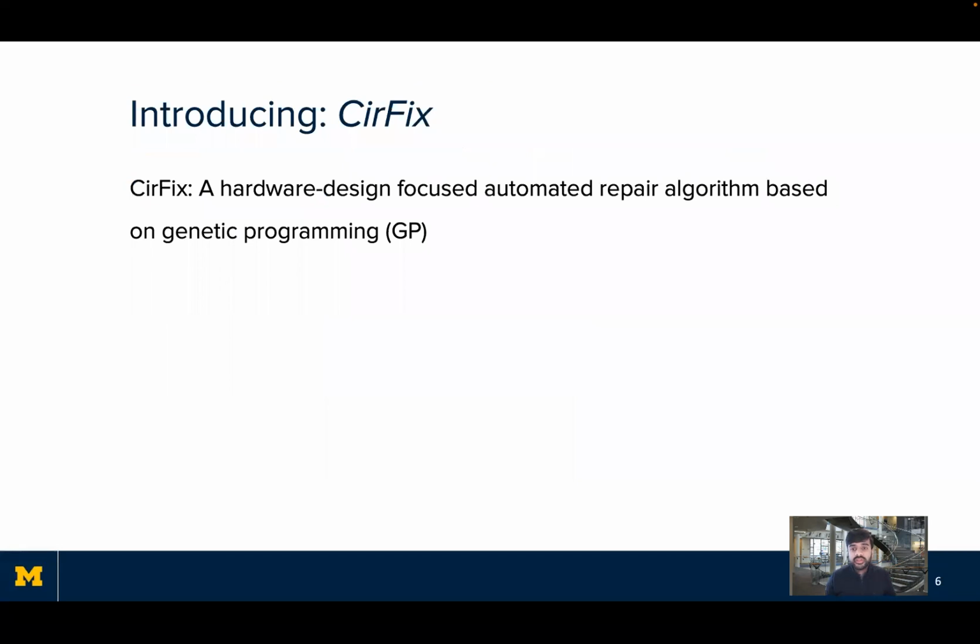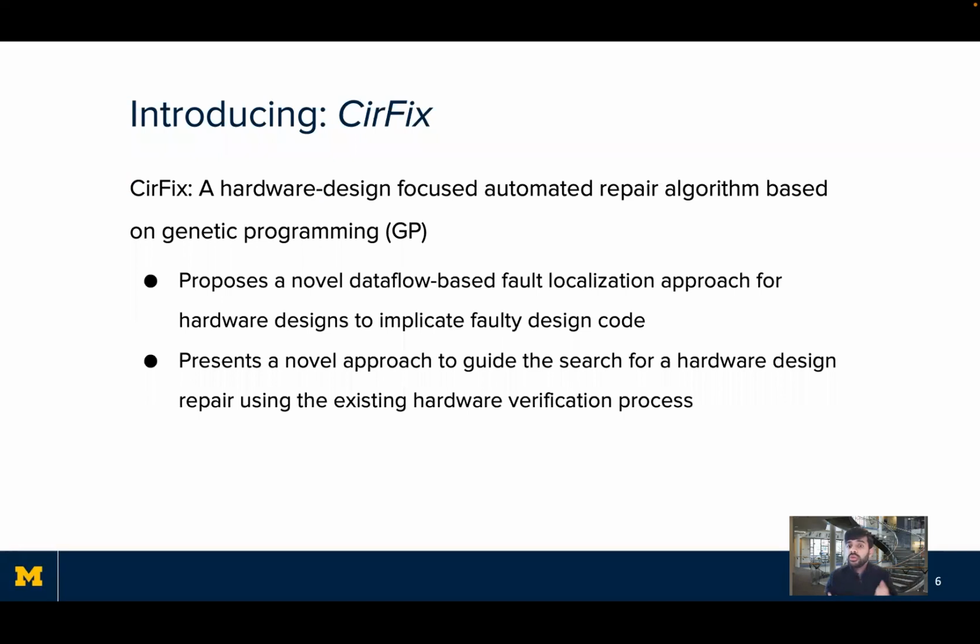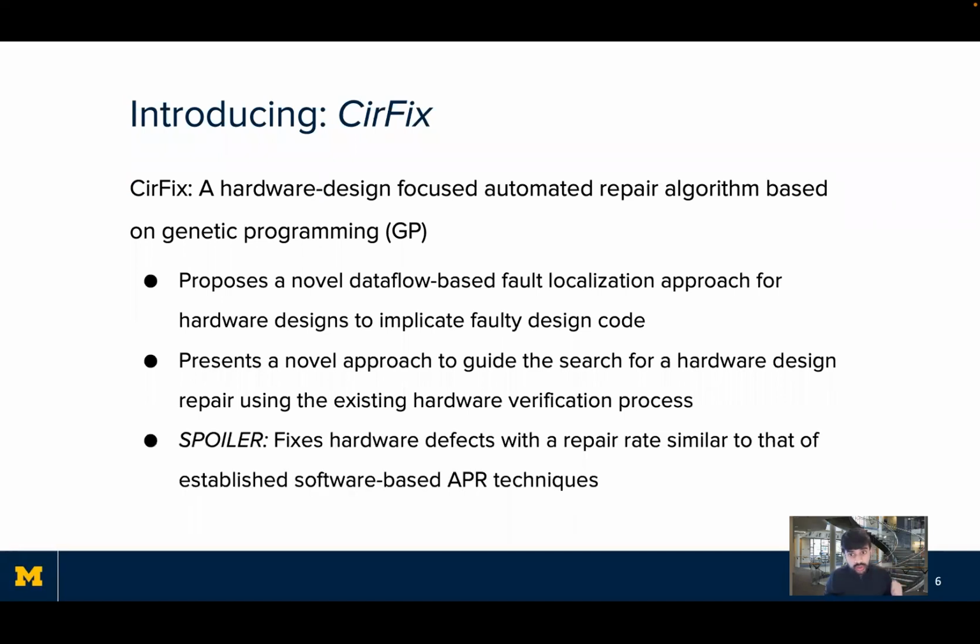Well, let me introduce you to CirFix, a hardware design-focused APR algorithm that solves the 2 problems I went over by introducing a novel data flow-based fault localization approach for hardware designs, and then also a new hardware domain-specific approach to guide the search for repairs. And then, spoiler alert, CirFix actually fixes hardware defects with repair rates similar to that of established software-based techniques, indicating that our approach is effective at bringing over the benefits of software APR to this new domain.